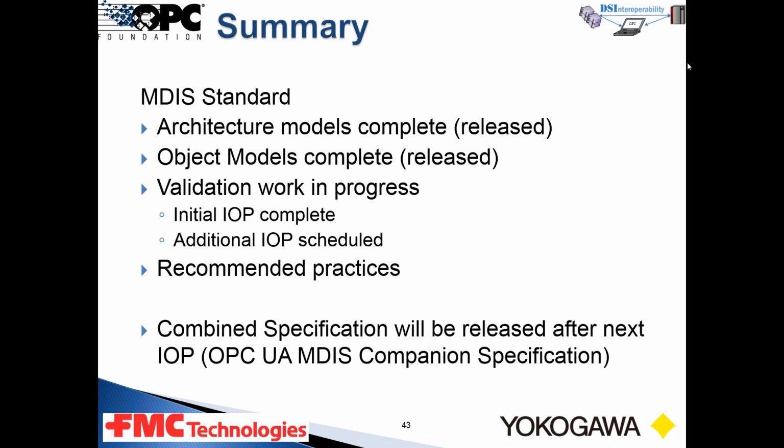This was extremely obvious at the IOP when client vendors, the DCS systems, were able to switch between servers in a matter of minutes. So you could switch to talking to a different system. In the old Modbus interface days, this would take tremendous amounts of engineering and a great deal of testing. Now it can happen very quickly, very easily.